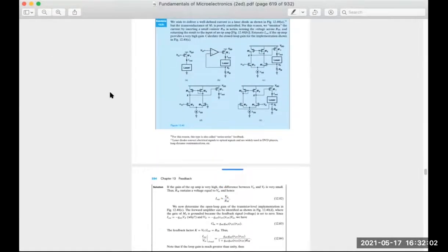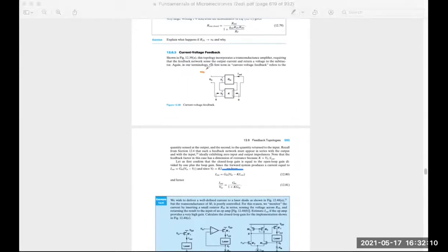Looking at the amplifier here, this input of this overall structure is boosted. Does it make sense with the feedback? It makes sense, right? Because this is a voltage amplifier. Input is voltage. So we want this amplifier input resistance to be big, right? Because this is the input. We want the biggest voltage here. So we want this impedance to be big.